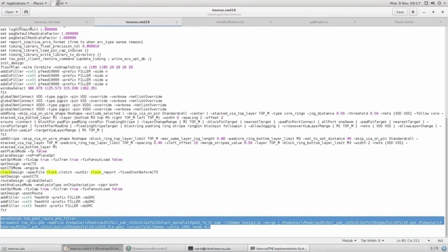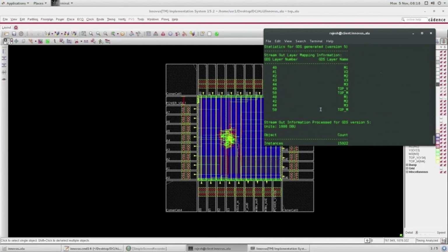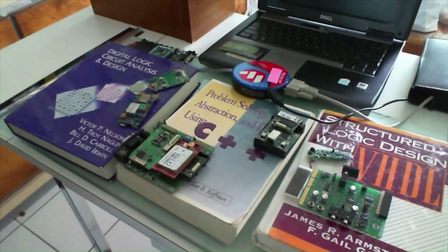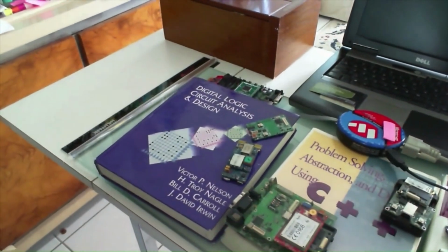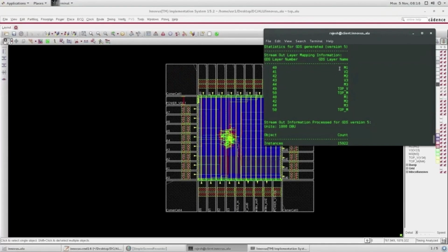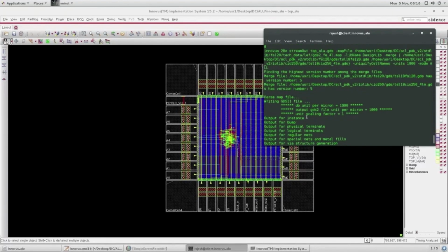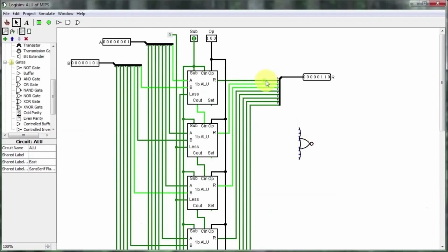Both simulated annealing and quadratic placement accept many controls. They include pre-placement, floorplanning, specification of circuits to be placed in adjacent locations, net capacitance, and source to sink resistance constraints, and weights for the various components of the scoring function, including net length, congestion, and population balancing.